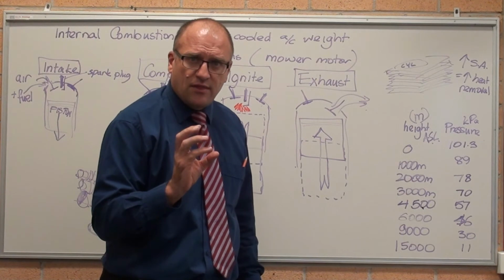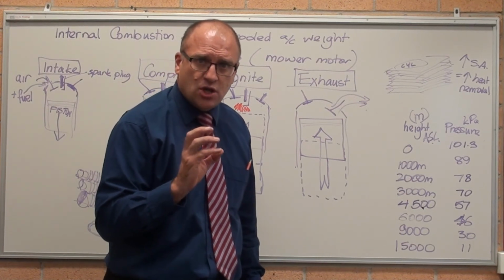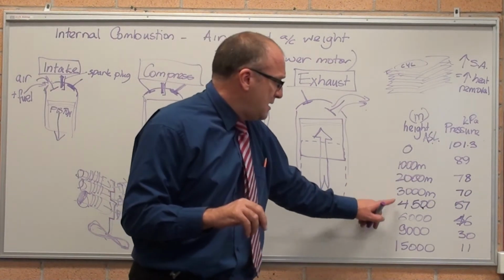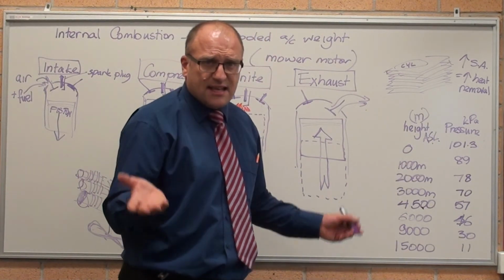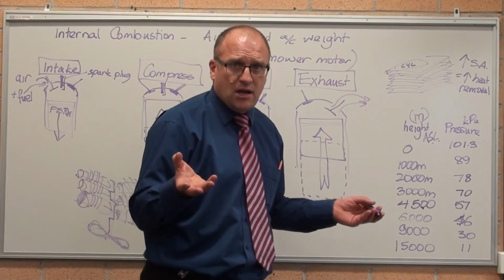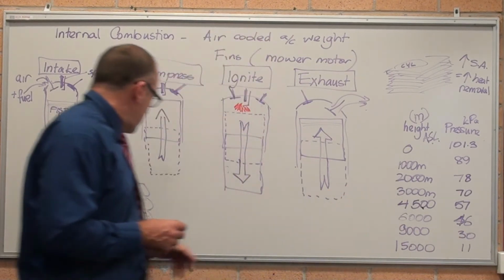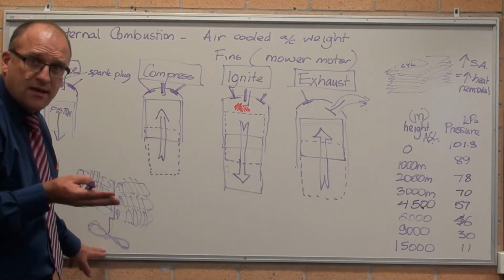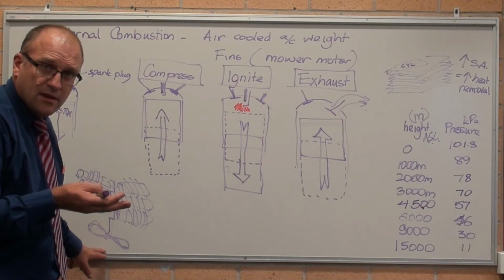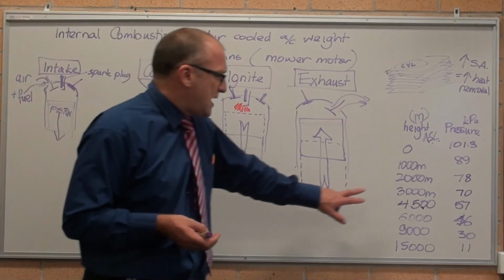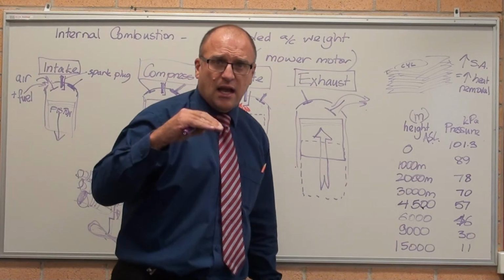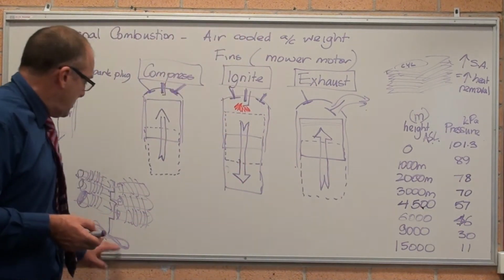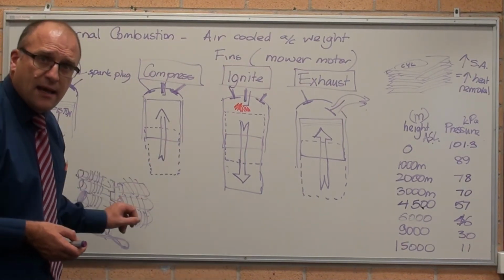You can't really run the propeller aircraft much higher for 2 reasons. One is it runs out of air to suck in. It just cannot get enough air to physically run any higher, as well as that propeller needs air to drive the plane forward. The higher up you go, the less there is for the propeller to work on. So really, a standard combustion engine can only go a little bit up in the air because it needs air for the propeller. The propeller needs air, the engine needs air.